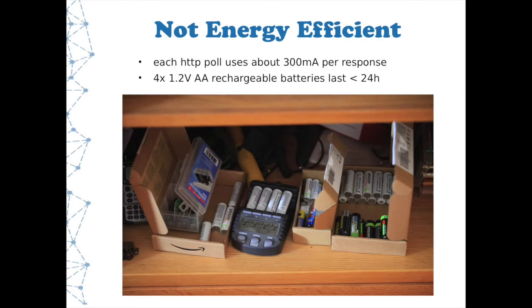So first of all, this is not an energy efficient solution. The web queries, if I'm doing regular data collection, has an energy cost. And I found that for AA rechargeables, which are at a lower voltage than regular alkaline batteries, they don't last. They almost last a day, but not quite. That's just a 5-minute web query to get that data out of it. So there's other ways you can approach this and save a lot of energy.